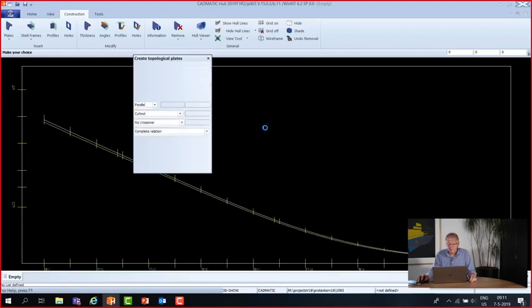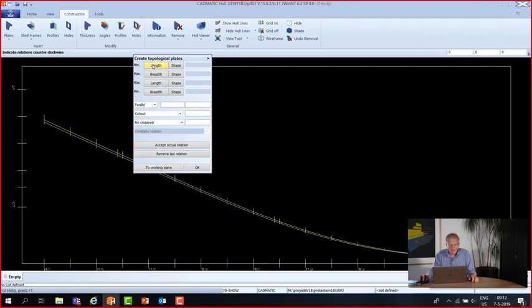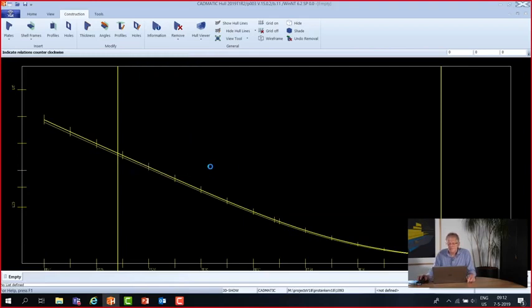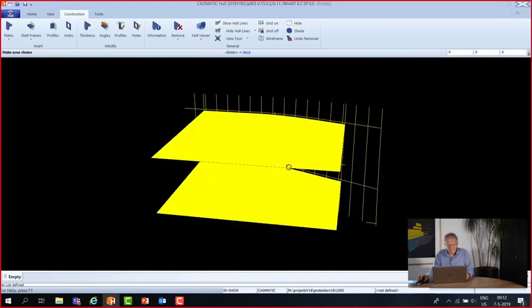Okay, from now we'll get a top view, and then we need to define the borders of the deck, and the aft border will be frame 26, but not exactly, it will be 650 millimeters in front of 26. Then we go along the hull line until the front border, and that one will be on frame 39, but again not exactly, 150 millimeters in front of it. And from center line it all starts at 7 meters. And then we can confirm this, and here we see the two decks.